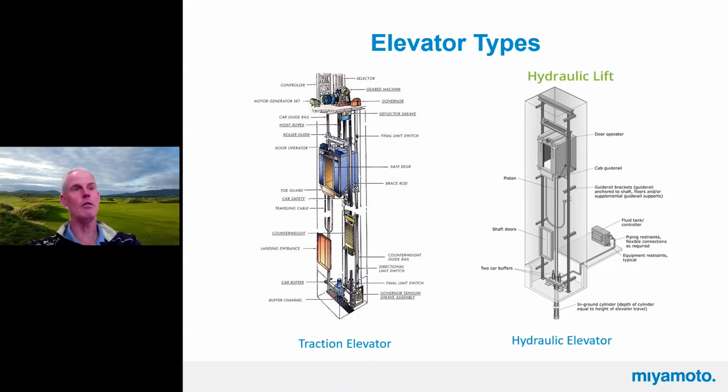Oh, the other thing too, I didn't really mention, but if you have a pit near a building footing, you typically need to look at dropping your footings too, so they don't surcharge the pit. So obviously we're always thoughtful about those, but yeah, good stuff.